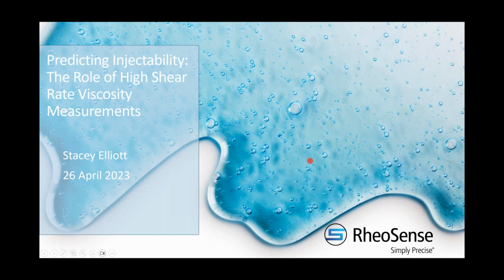So you can find these relationships. The shear rate is going to be related to that volumetric flow rate, and then the inner radius of whichever portion you're looking at. That shear rate is going to be proportional to that inner radius to the inverse third power. So when you think about something like this needle, which has a very small inner radius, the shear rates in the needle can get quite high. Depending on the needle gauge that you're using and how rapidly you're trying to deliver this, it's going to be somewhere in the tens of thousands to hundreds of thousands inverse seconds. So it can be quite high.